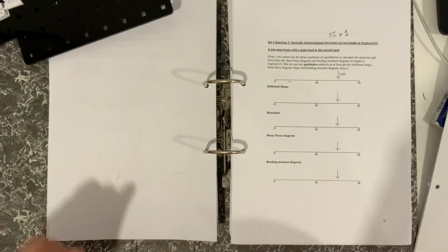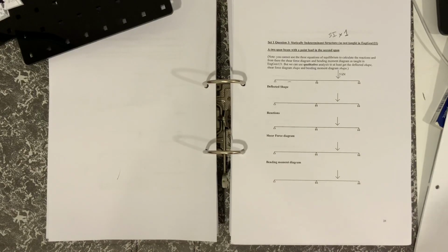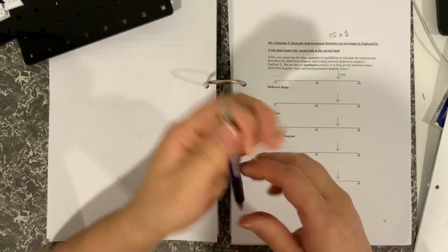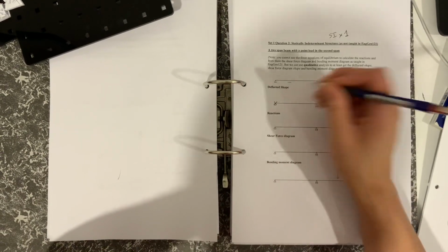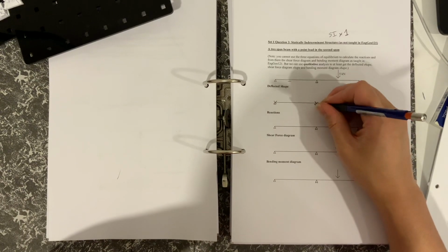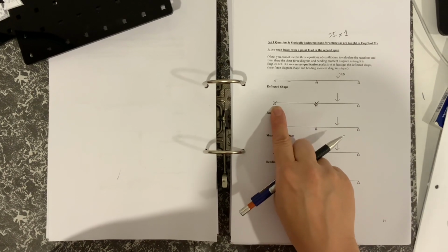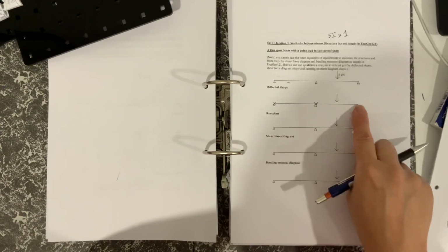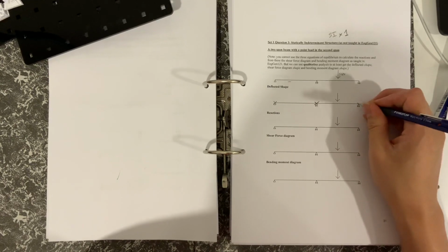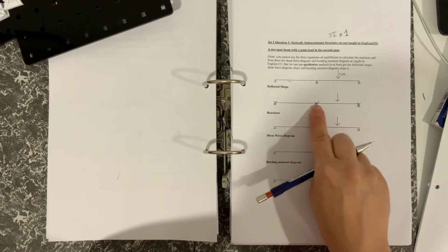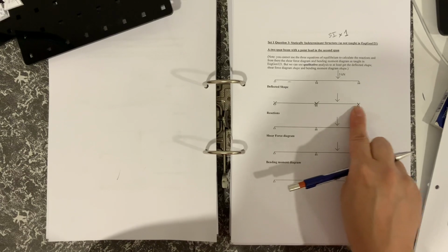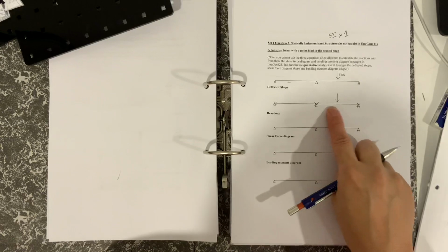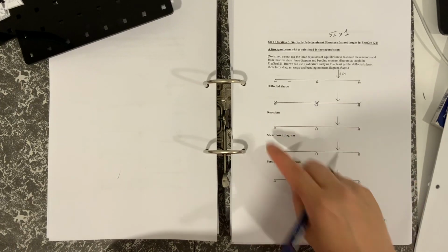But as we can see from the prop, there is curvature. So the deflected shape, let's start here. So that one doesn't deflect, that one doesn't move downwards or upwards. This point doesn't move downwards or upwards, and this point doesn't move downwards or upwards. But of course, these two are allowed to move in these two directions, otherwise you're getting stressed, you're getting tension action or catenary action in the beam.